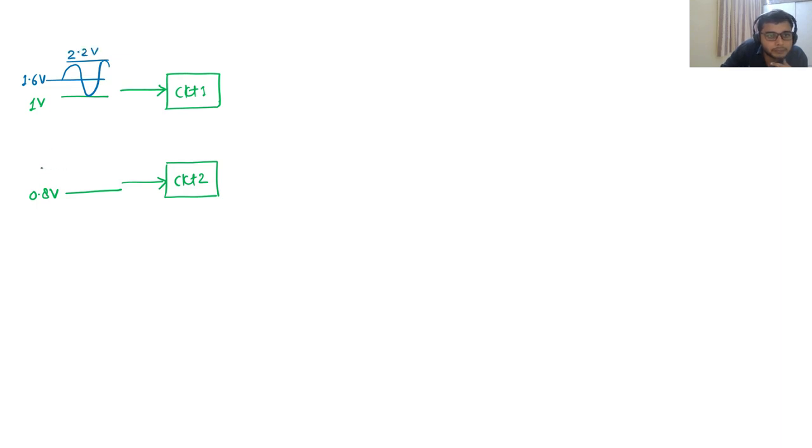But for the same circuit whose common mode is 1.6 volt, with access down to 0.8 volt, with symmetric swing it can go above to 2.4 volt. So at the input there is a possibility of larger swing, or we would have more flexibility when we drive these circuits from the common mode point of view.